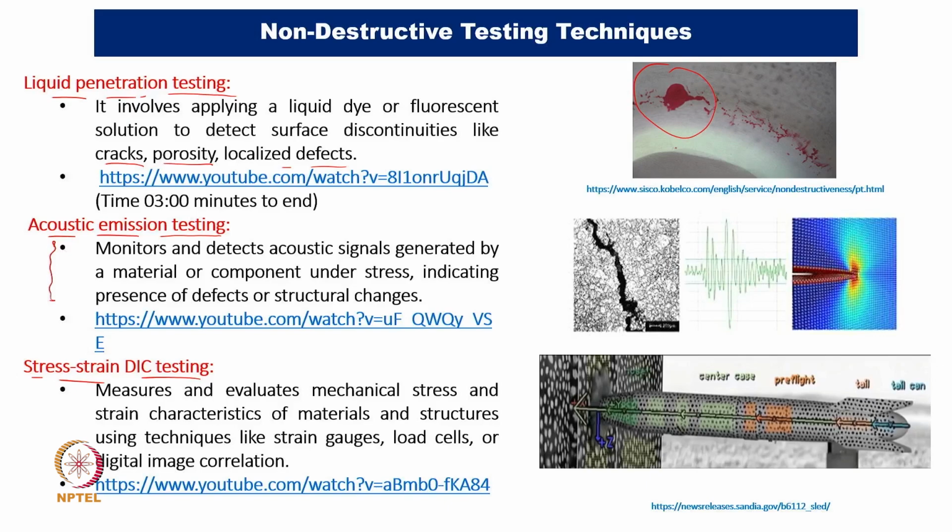However, many times installing the sensors will be a kind of problem. Particularly, we covered in the previous lecture that using a sensor on a rotating element is far preferable. It will have a high signal to noise ratio compared to when we are attaching it to a unit which is stationary and a bit far away from the location of errors or flaws.